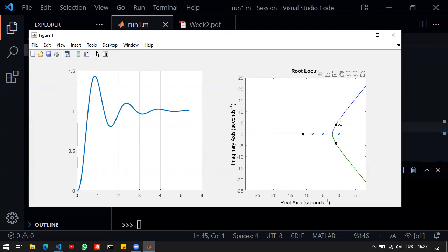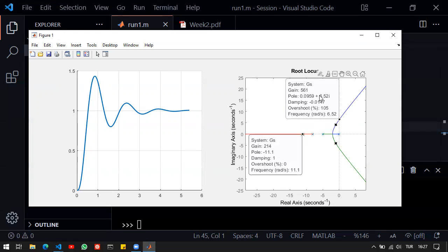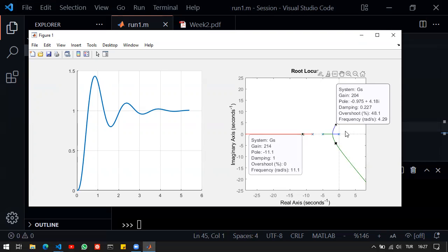But there's also a risk that we might touch j omega here, which is basically the marginal stability boundary. Therefore, I might end up in unstable solutions. But there's a certain point, for example, the settling time value at this point here that we've already designed, that seems to be working, because our strategy was to have two poles dominant and one of them non-dominant and far away. So this works here because the root locus also moves in that way.